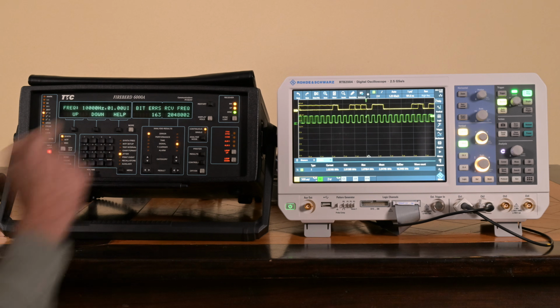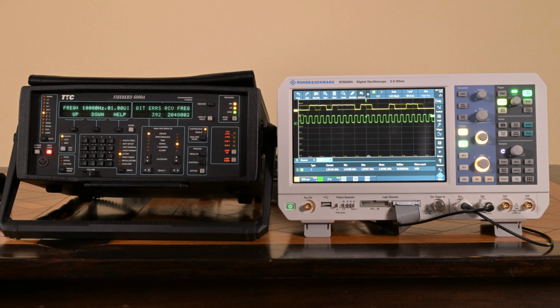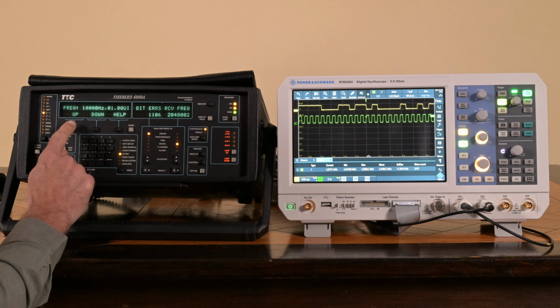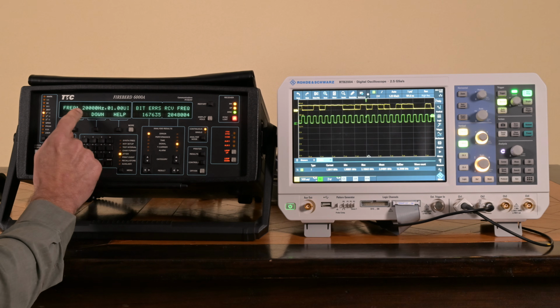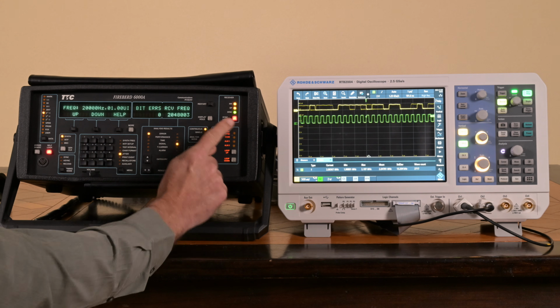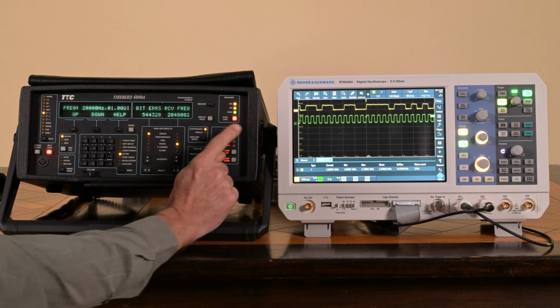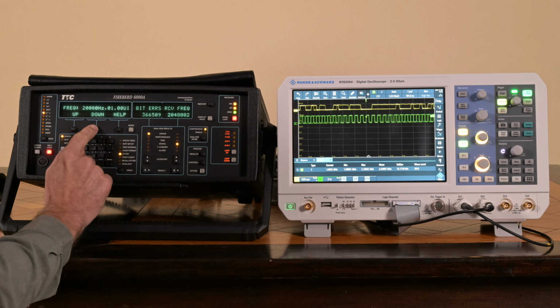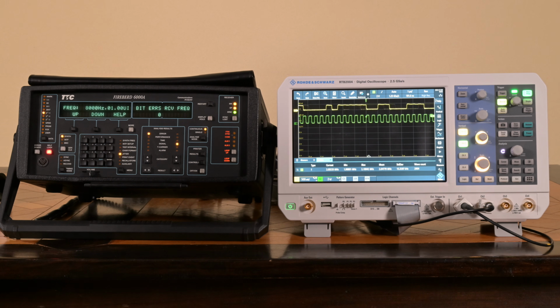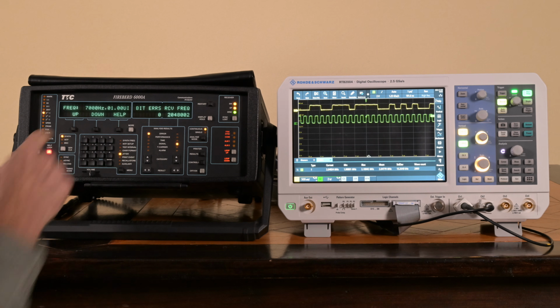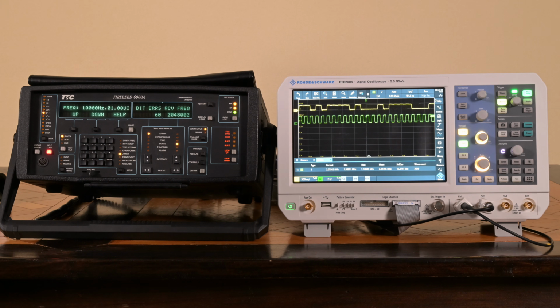9. Ooh, at 9 we're going to see some occasional errors. Not that many, we got 600 errors on the 2 megabit link, but at 9 we start to see errors. And when I went from 10 to 20 kilohertz, it's getting very bad. We're only getting errors, and it even lost the entire sync of this unit. So let us bring it back to 8 and reset the device. At 8 kilohertz of additional jitter, we are still good. At 10 kilohertz, we're going to see the first amounts of errors here.